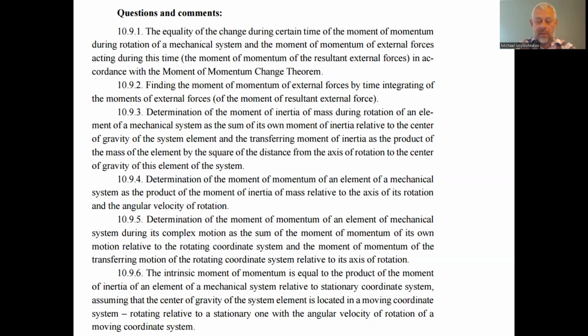If the axis of rotation does not pass through the center of mass of the mechanical system, we have to consider first the inertial characteristic of the rotation of the system relative to its center of mass, and the rotation of the center of mass of the mechanical system relative to the assigned axis of rotation.